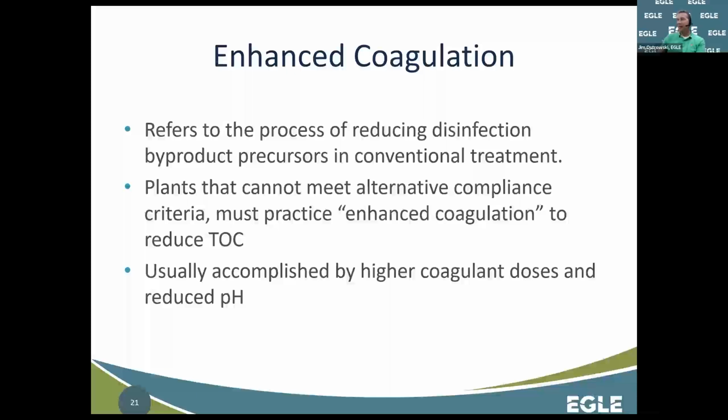Ways to determine the optimal coagulant dose include all the following except. Well, add color to distinguish the flocs is the one that I would go for probably. I'm sorry I didn't touch on jar testing. That's a very common way for folks to evaluate different coagulants. I should have touched on that. Of course, the visual observation we discussed, and we didn't get into zeta potential yet either.